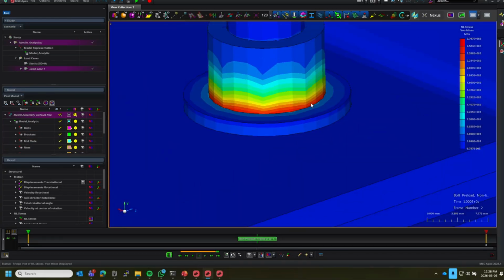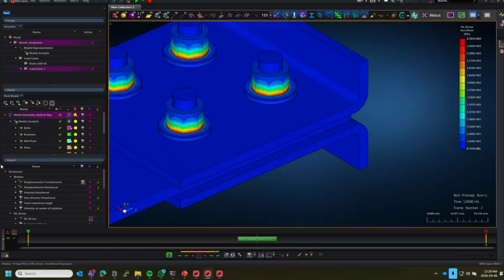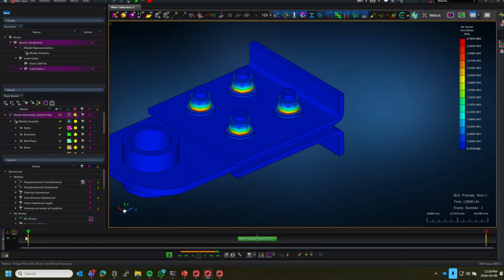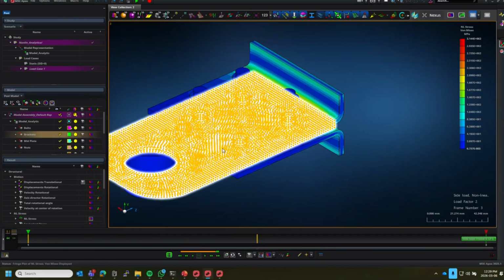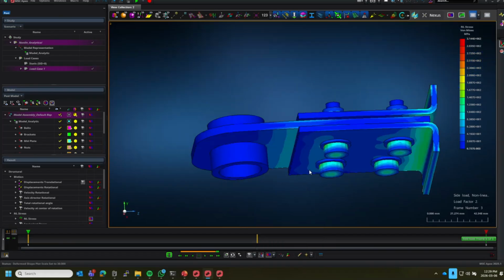It's kind of expected to see higher stresses in at least some spots, obviously on the nuts and the bolts and so on. But this is just a preload. If I then go to the next step, I'll see as expected this has been bent. And notice that in Apex by default, if you've got SOL 400 runs, it switches to true scaling because that's the actual deformation. It's seldom a good idea to do relative, especially for contact, but since everything here started in contact, it may make okay sense to plot what this looks like. So there you can see that part has been bent a bit.